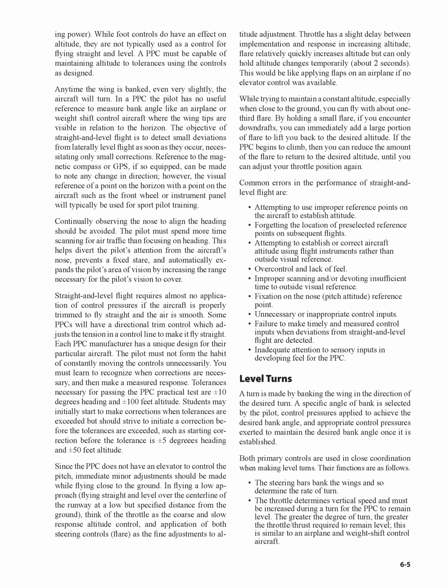Throttle has a slight delay between implementation and response in increasing altitude. Flare relatively quickly increases altitude but can only hold altitude changes temporarily, about 2 seconds. This would be like applying flaps on an airplane if no elevator control was available.